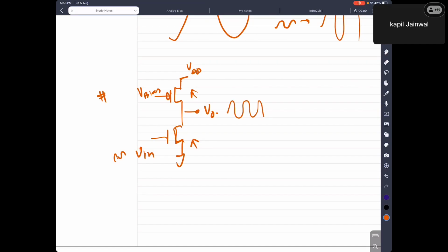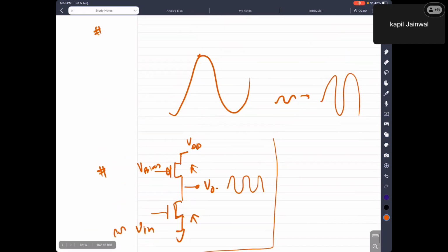And of course, when you use simulators, they have to be very advanced, because all these analyses are not simple in nature, and they need a lot of mathematical equations to be solved. So specialized software is used, which is available to us, like Cadence, Synopsys, Mentor Graphics. So we first do the simulation at the schematic level. Once we are done with the schematic level simulation and satisfied that we are getting the performance, then we go for the layout design of it.